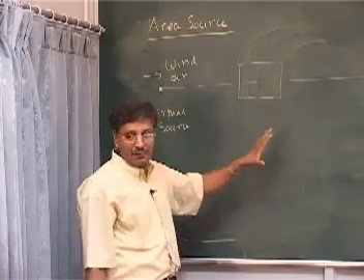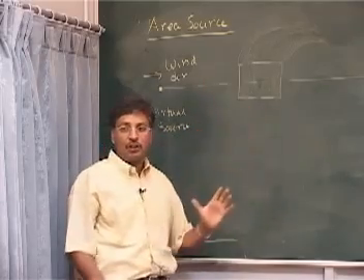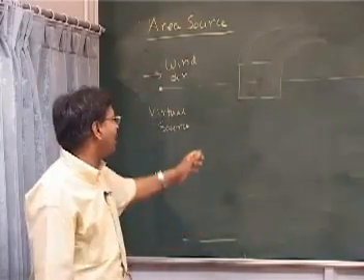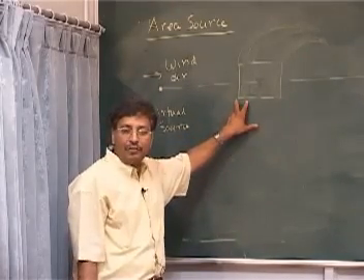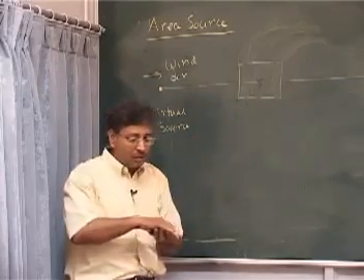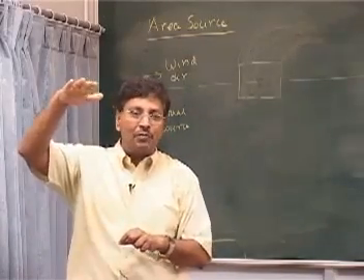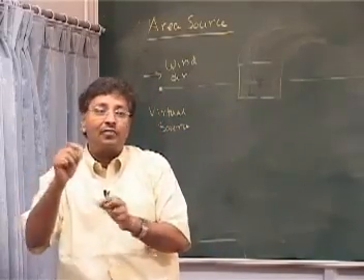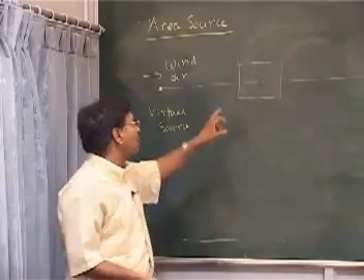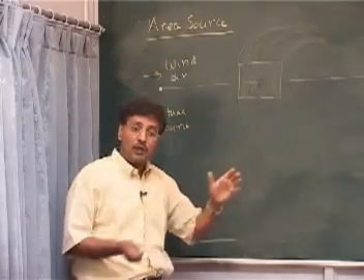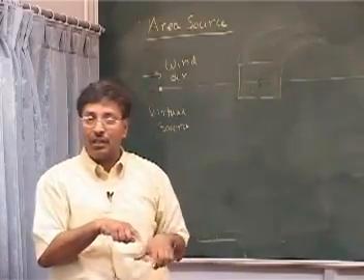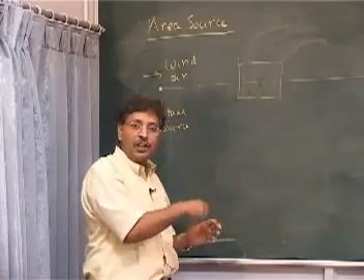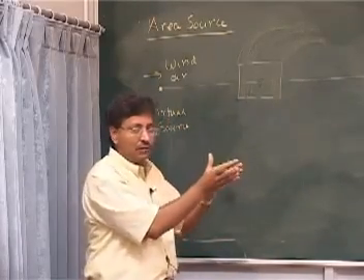So in order to get an estimate, okay, you want to apply such a thing where you can quickly see what is happening. Okay, but you can certainly divide it into a grid of 500 meters or half kilometers. You can not only divide the grid horizontally, you can also have a grid which is a function of x, y and z. You can solve the equation in every little grid, okay, and find out the concentration. You can also not only model the concentration, you can model the wind vector also. Suppose you strike a building, the physical factor has gone into your model, okay, or GIS based, then the wind cannot go this way, so it turns this way.